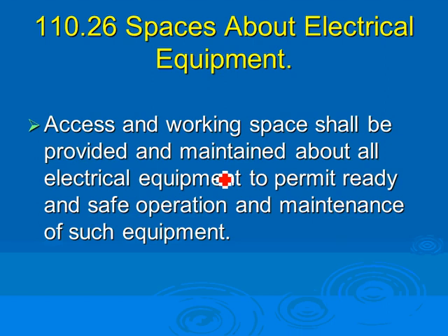So you have an arc flash boundary that you have to maintain based on 70E. The NEC code book 110.26 gives you the minimum clearances around electrical equipment. I was talking to a couple of guys when we were eating, saying that we need more space around the equipment, and I said as engineers we always go to the architects with double the value.